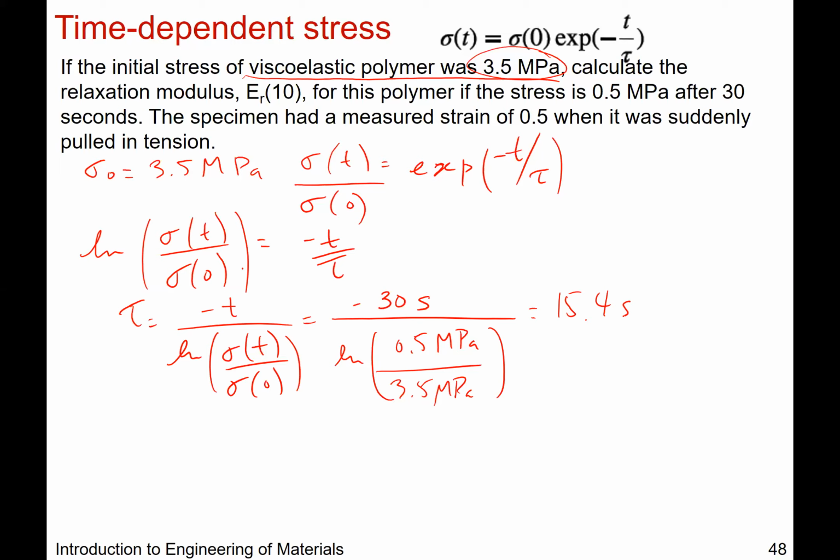So if it takes 15.4 seconds to relax, I can calculate what my stress is at 10 seconds, because I have the relationship. Let me be clear with my units so there's no confusion. This is not a 5, this is 10 seconds. My initial stress sigma naught was 3.5 MPa, so I can plug that in.